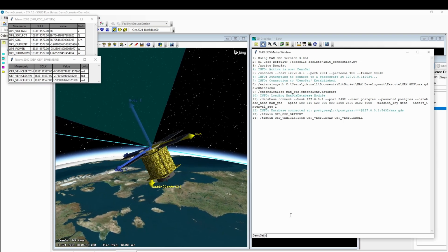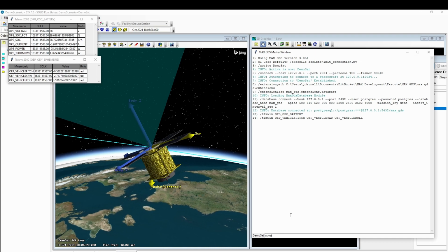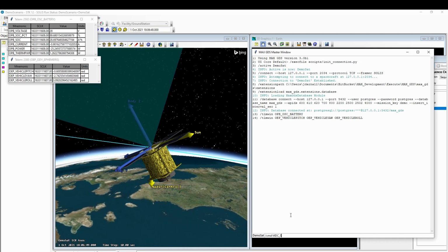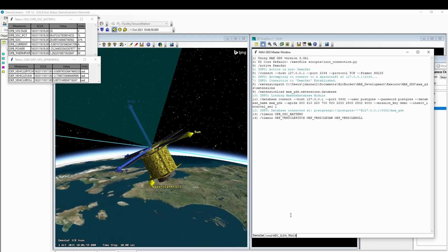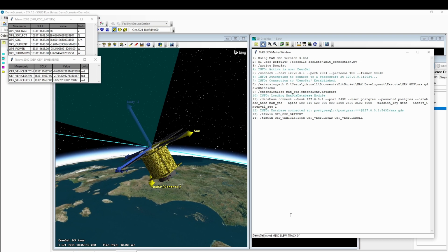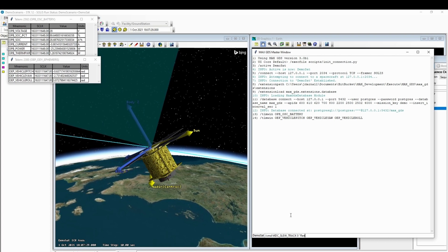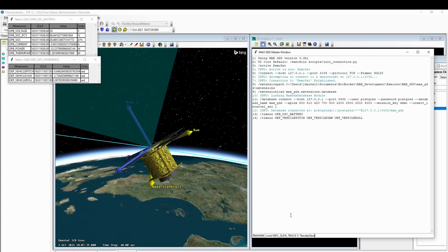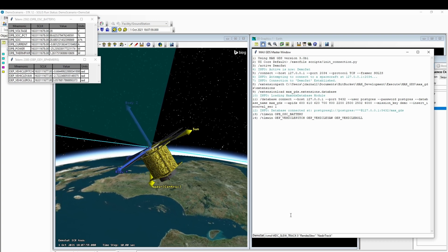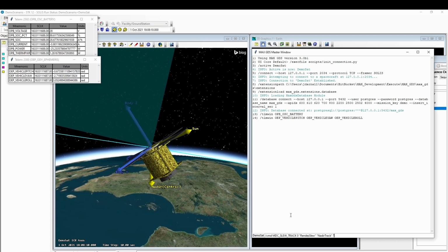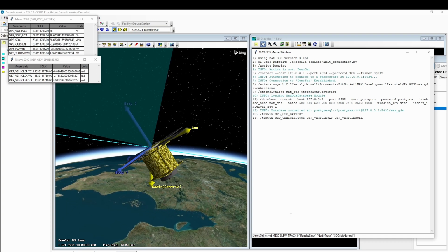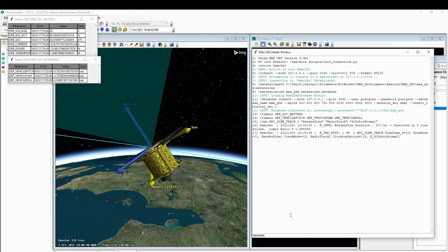The other thing you can do is issue commands just as if it were on orbit. So let's run the same command that we were running earlier when we were commanding the slew of the spacecraft. So let's issue the slew track command. The slew time is 0. We're going to use rendezvous slew as the slew mode. We're going to go to nadir track. And our clocking option, we're going to use spacecraft orbit normal. We issue that command.